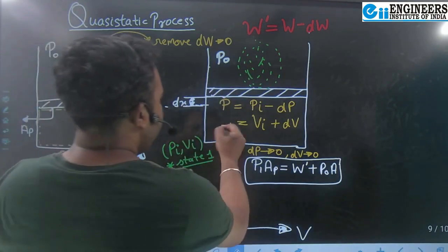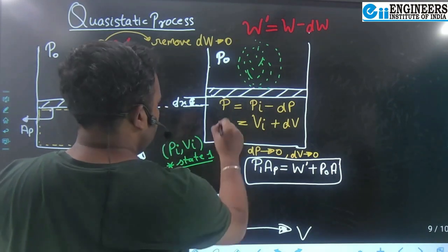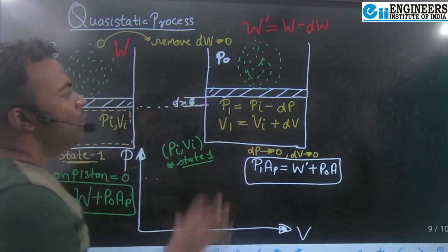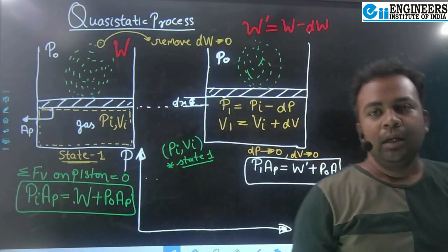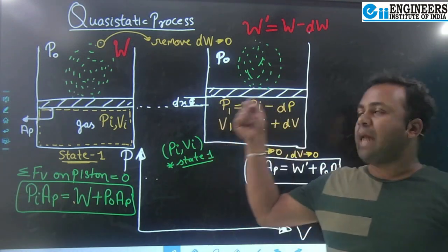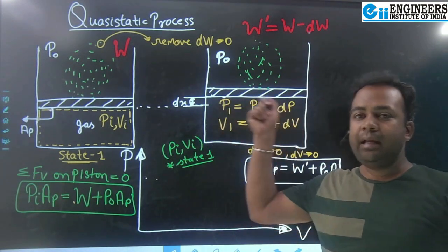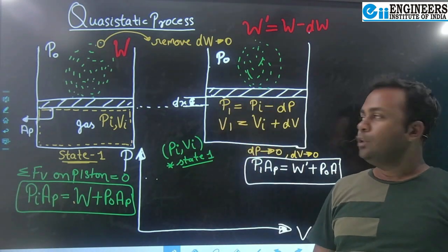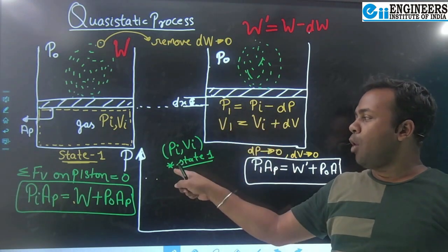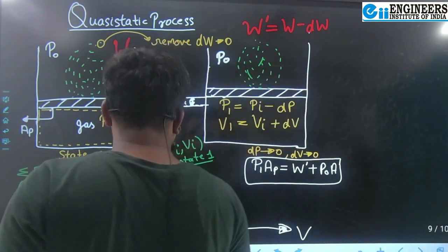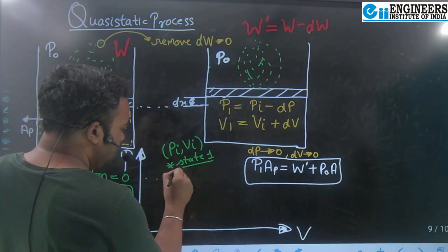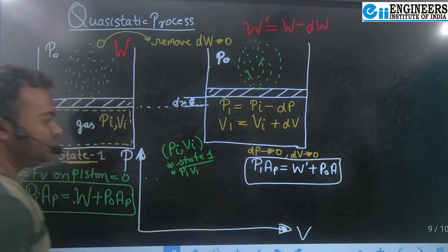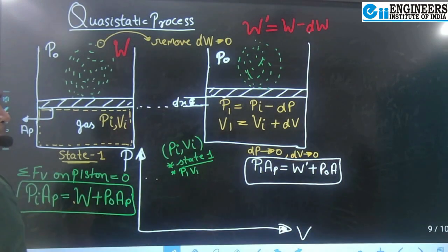So now we can see there is equality of pressure everywhere and equality of properties everywhere in the system, right? Because thermodynamic equilibrium is established now, the properties are fixed and the state is also fixed, and the state is described by this P1 and V1. So I can register this P1 and V1 and plot it on my property diagram. So this is another state, P1, V1. The new equilibrium state is P1, V1, right?